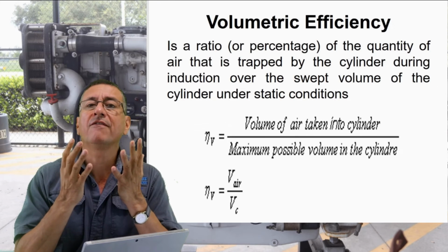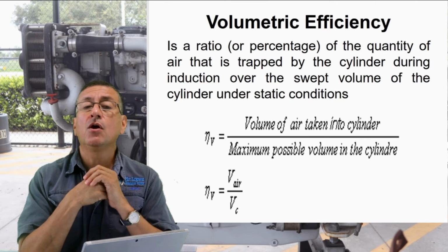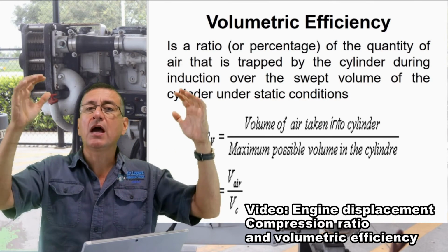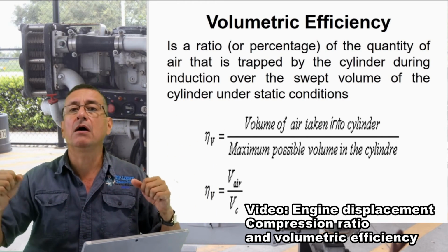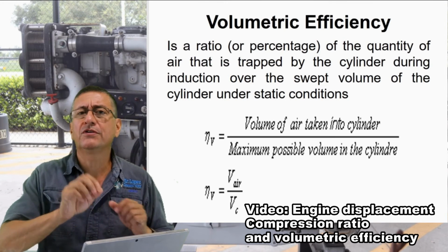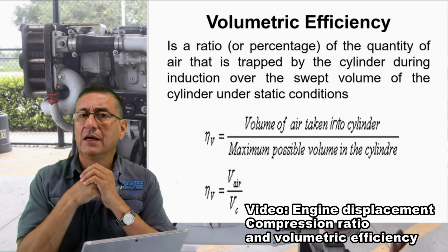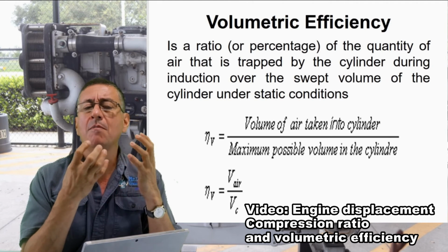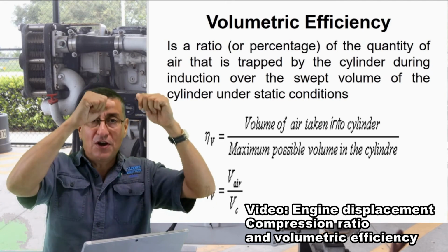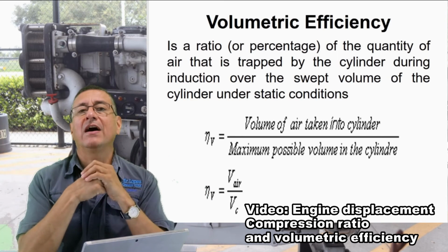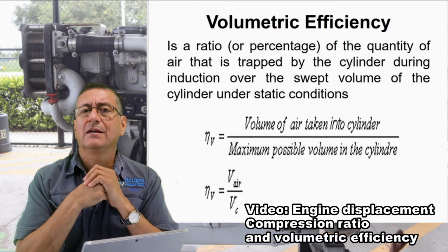There is volumetric efficiency. Right now, with the formula of the engine displacement, we calculate in theory how much air my engine sucks in when the pistons are going down. 5 liters or 4.7, according to the formula. But this is the ideal. How much is the real amount of air that enters the combustion chamber at this moment when the pistons are going down with the intake valves open? It's not 4 liters, it's 3.83.